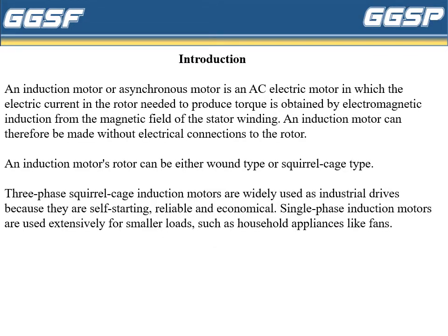Introduction. An induction motor or asynchronous motor is an AC electric motor in which the electric current in the rotor needed to produce torque is obtained by electromagnetic induction from the magnetic field of the stator winding. An induction motor can therefore be made without electrical connections to the rotor. An induction motor's rotor can be either wound type or squirrel cage type.